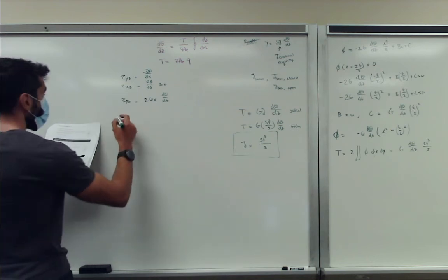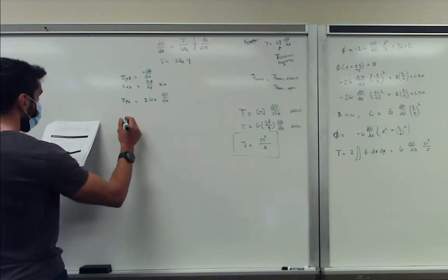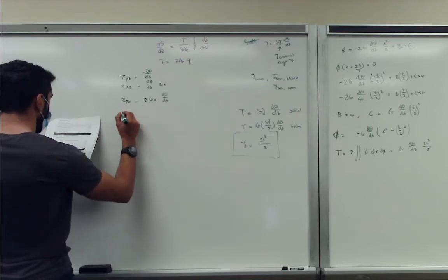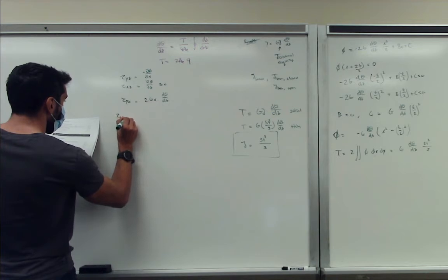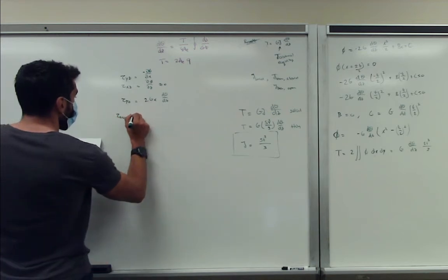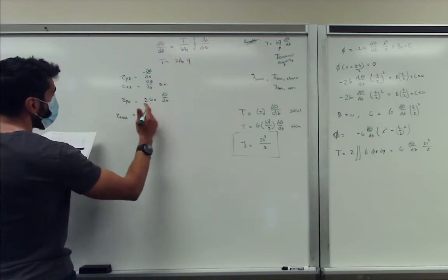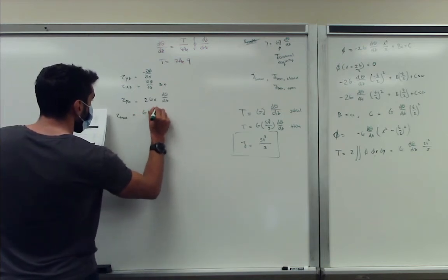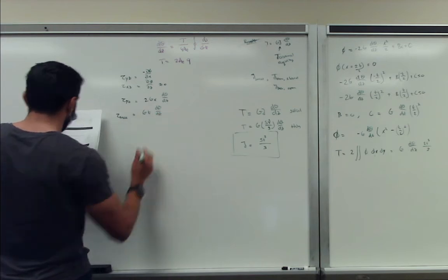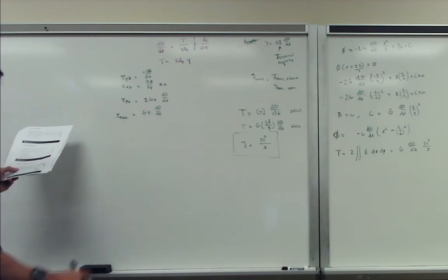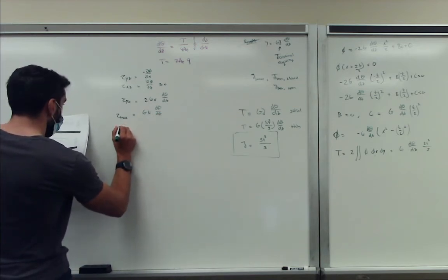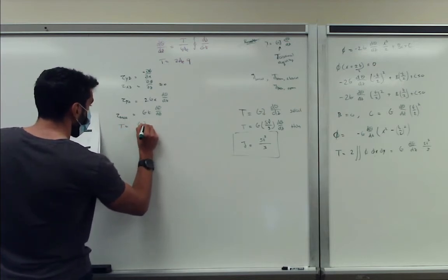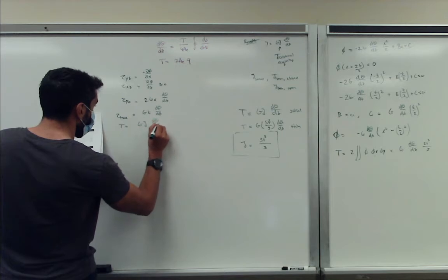If we look at the maximum, the x direction must be equal to t over 2. So we get G t d theta dz. And if we look at the torsion, we get it in terms of d theta dz.